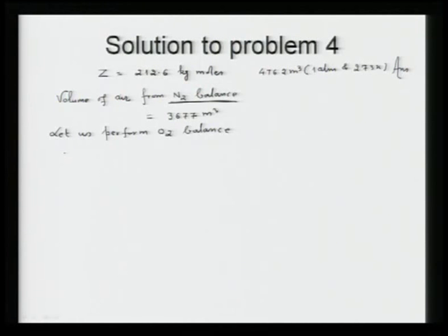So, let us first calculate the oxygen moles in the gas. That will be equal to 212.6 × 0.26 upon (2 plus 0.13), which is equal to 55.3 kg mole. This is the total oxygen available in the gas, but mind you, this oxygen consists of oxygen from air as well as oxygen from the charge. So, we have to subtract that oxygen from the charge.